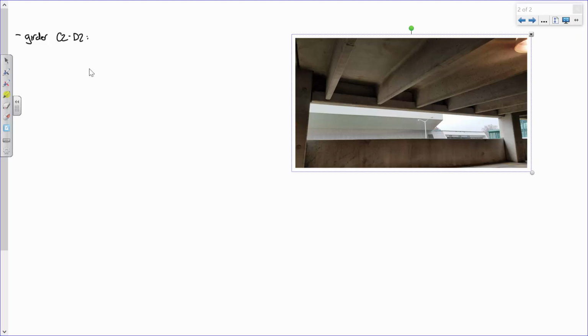Look at this image, right? I have a floor beam that goes from here over to the next adjacent girder, right? The ends of those girders, let's say they're seeing what, 3,000 pounds? So if I was looking at, let's say, that girder, I propose that I've got a girder that looks like this, but everywhere that I have a floor beam, like right here, I'm going to have a point load. Right here, a point load. Right here, a point load. Right here, a point load. What are those point loads? The reactions from the floor beams. Make sense? See what I mean?